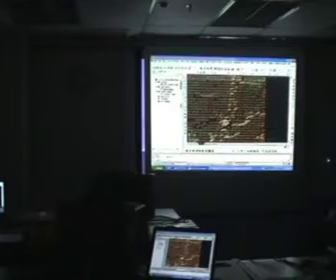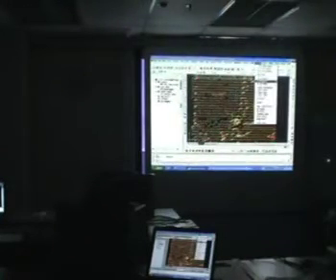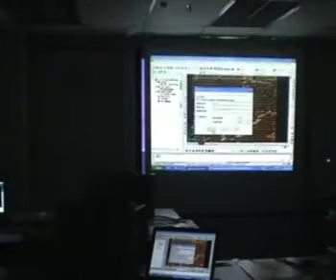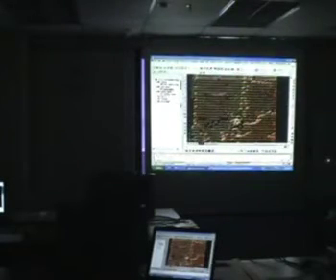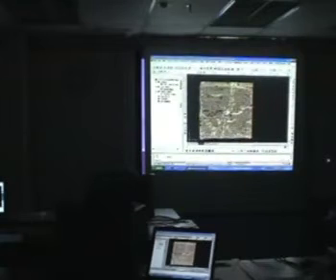Now let's say we want something a little bit more permanent. We want to have the triangles stay there and we view them in 3D as well. We can use 3D faces. So I'm going to click OK. So now even if I redraw, it's still there. So I'm just going to show you what it looks like in 3D.